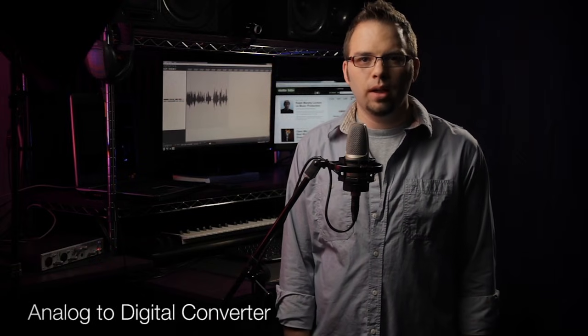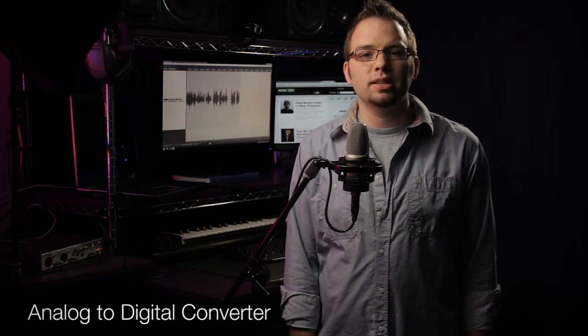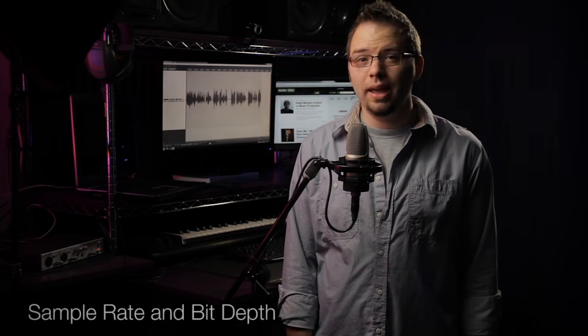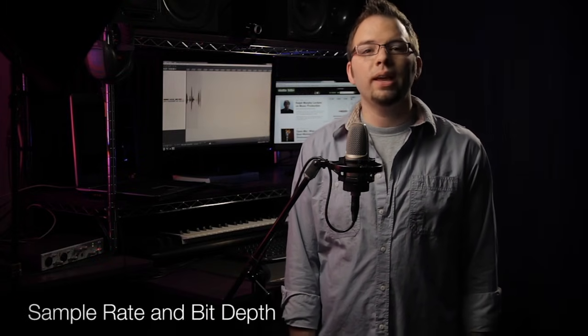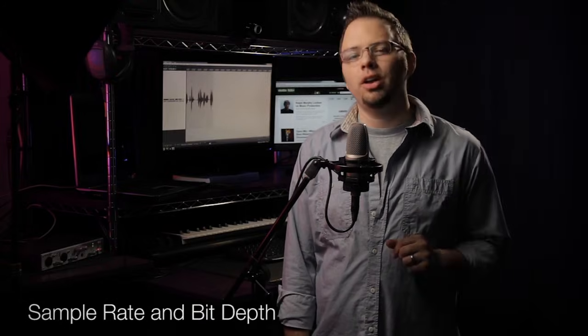All digital recording will need some sort of device for the analog signal to be converted into digital bits and bytes. When the analog audio comes in, either by microphone input or line input, it gets converted with an analog to digital converter. When you're looking at audio interface specifications, 2 terms that you'll come across are sample rate and bit depth. Without going into too much detail, let's talk about each one of these.